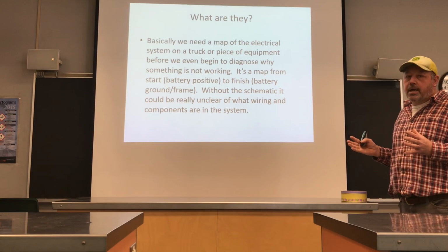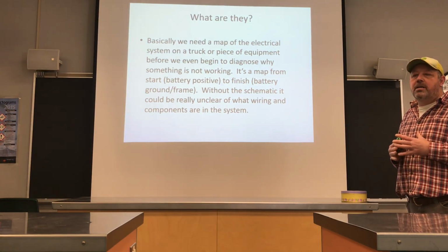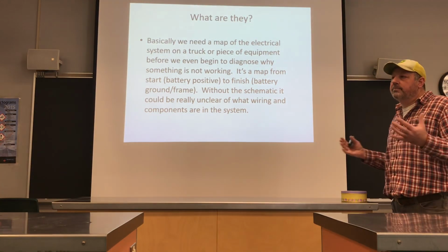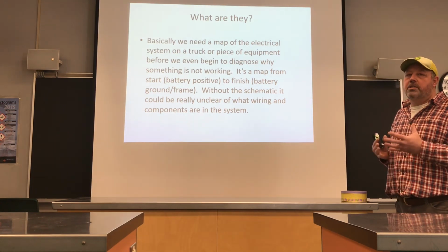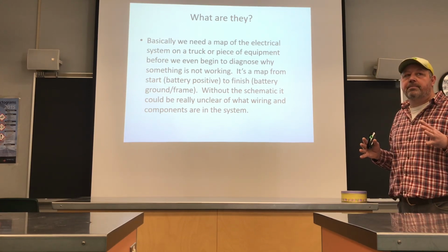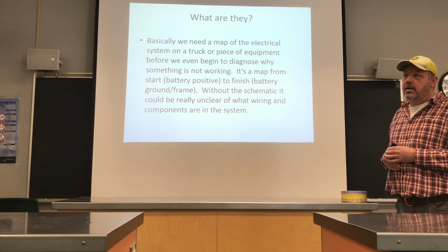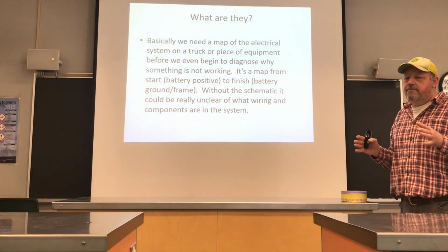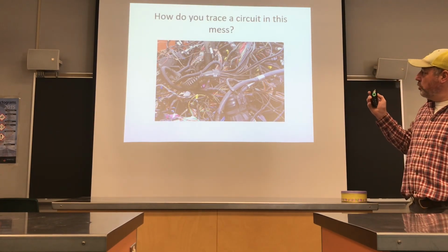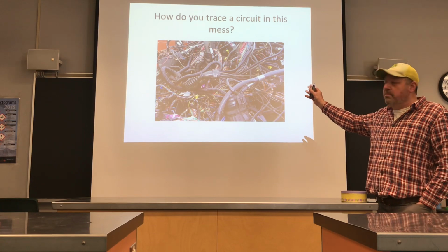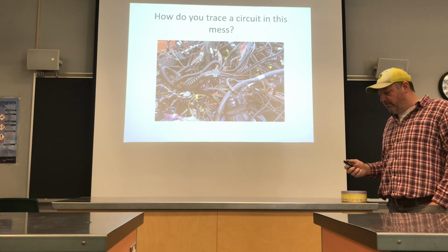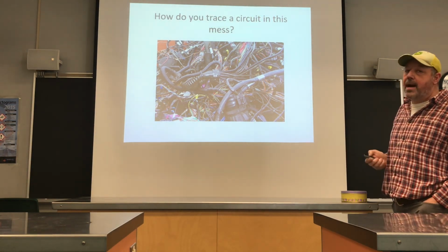So in general, when we look at a wiring schematic, it's basically going to show us a map or a road map, however you want to visualize it, of all the different circuits on that particular machine. So it's going to give us a lot of information on one picture. So we do have to be able to visually break it down. When you look at something like this, it would be very hard to pick out where exactly our problem is if we can't break it down from circuit to circuit, which is where our schematic is going to come in.